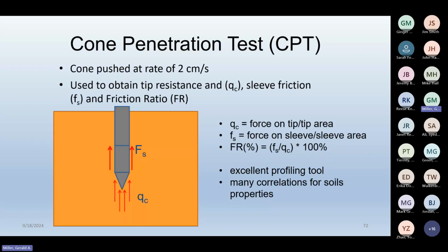Once you get air inside that sensing element, you then get what's called hydrodynamic time lag, because the air is compressible. To transmit pressure to the pressure transducer, the diaphragm, every change in pressure out here has to go through that porous fluid and hit that diaphragm.